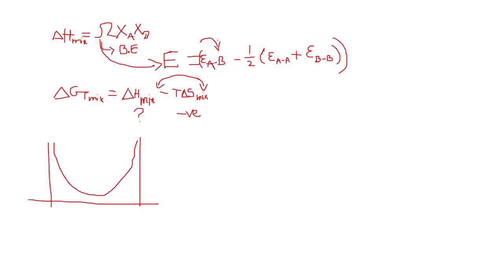So these are the type of compounds which form stoichiometric compounds. For example, Fe3C. Right. So there you can see the long range ordering. Wherever you look, each carbon atom is surrounded by 4 iron atoms or 3 iron atoms, right? So Fe3C. Each carbon atom is surrounded by this many iron atoms. Now that is known as cementite type. Now that is for the case delta H mix is negative.